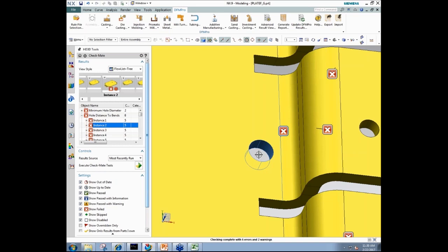This hole diameter can get deformed. So if you want to avoid that deformation, or if you have some tight tolerance requirement, you will have to at least let the manufacturer meet this tolerance requirement on this hole. So probably it is a good idea to bend it first and then make the hole. But then you are definitely making a plan for having that drilling operation after the bending.